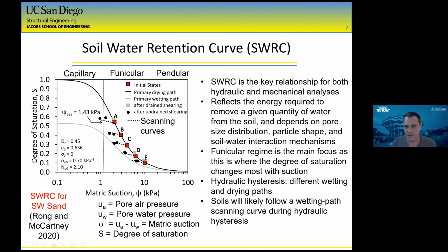We need to think very carefully about hydraulic hysteresis, which means different paths of wetting and drying that are going to happen. And usually in some experiments that we've already performed, we've seen that if you're starting on a drying curve, the seismic compression process is going to lead to a wetting scanning path.